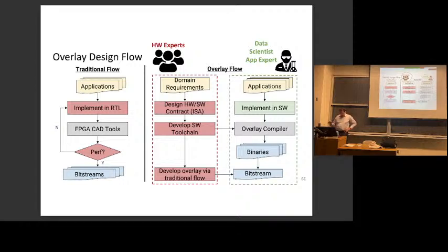They basically then develop two things. They develop an instruction set architecture, instructions that are going to control the hardware, and they develop a tool chain that can produce those instructions. So basically a software compiler somehow. It doesn't have to compile arbitrary software. For this particular example I'm going to show you, it just needs to understand sequence processing neural networks, but it has to be able to create instructions from those.